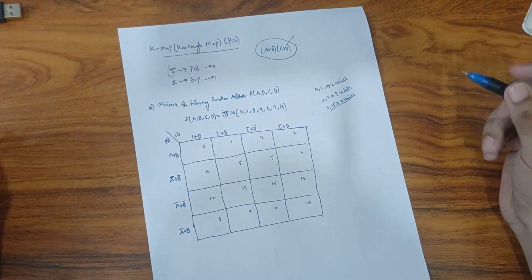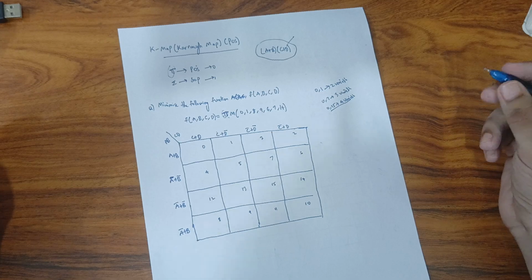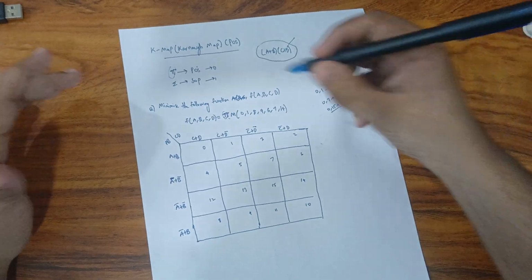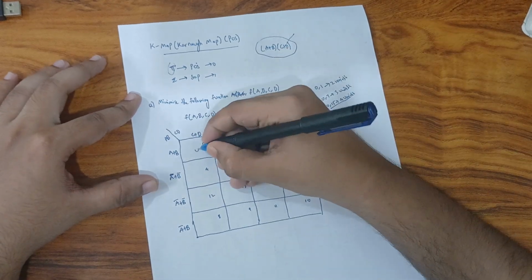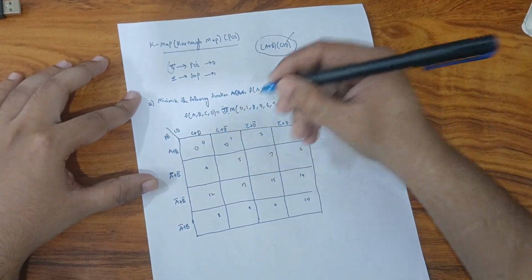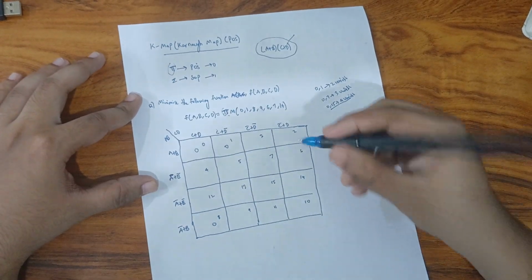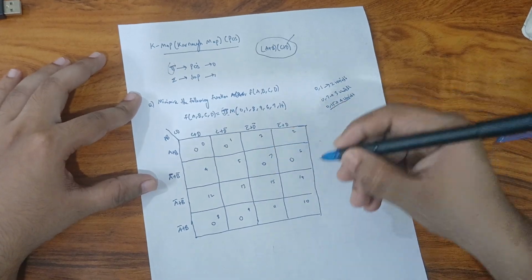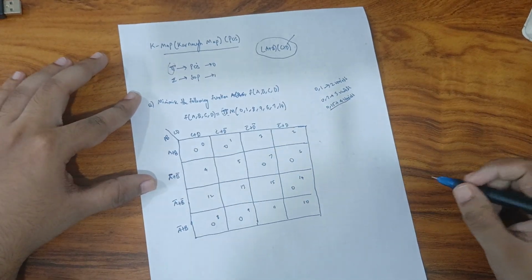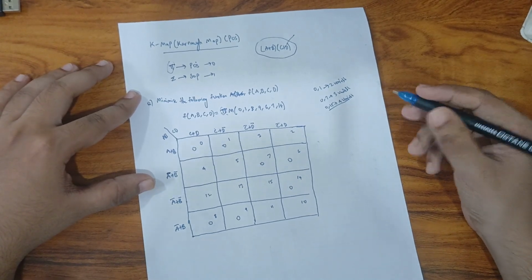It's basically the same as the SOP term. So let us get started with the min term substitution. So we need to substitute a 0 at 0th position, and at first, and then the 8th position, and then the 9th position, then the 6th position, and the 7th position, and then the 14th position. So we got our min terms sorted, and now we need to go for the grouping.